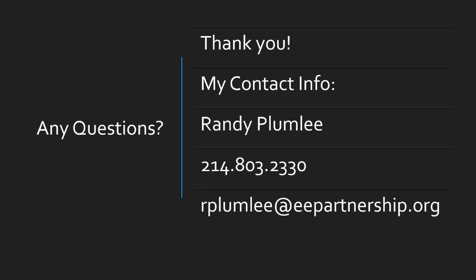The other big failure are these water heater housings for your tankless water heaters. There are all kinds of issues with those because you can't even put a drain pan in them, and they are inset in the wall. Those have to be head flashed, and they're not putting any flashing down the side with peel and stick. They're not doing any of that, and those are huge leak issues. It does have to have a weep screed or some type of head flashing because that's a stucco termination above that water heater. If I'm involved, I make them put the flashing in there, but a lot of times I'm seeing them after the fact. So it's just another failure point that we have to look at and address.